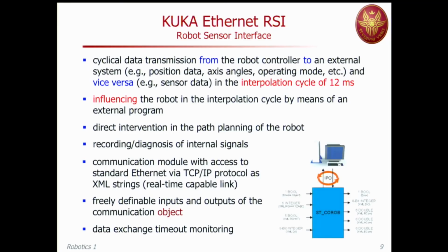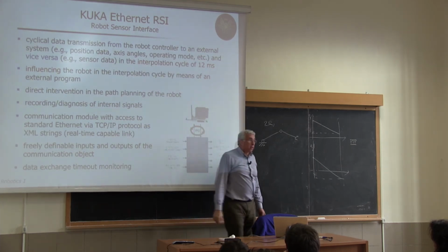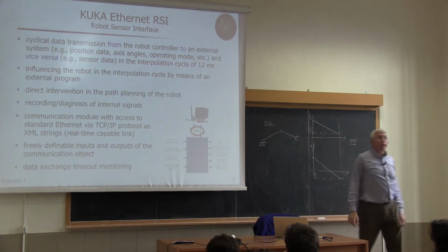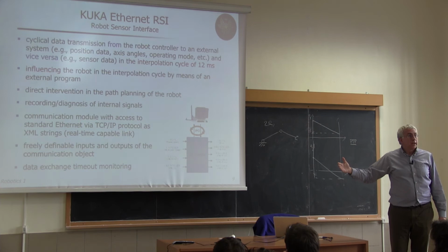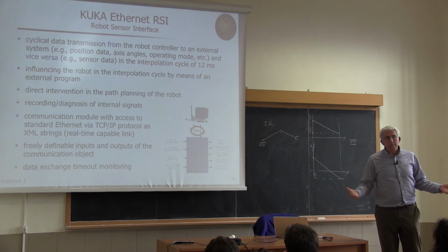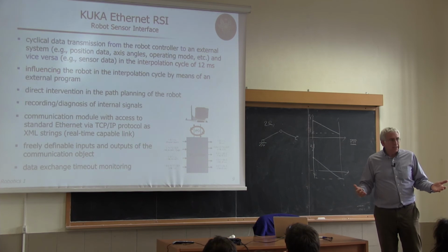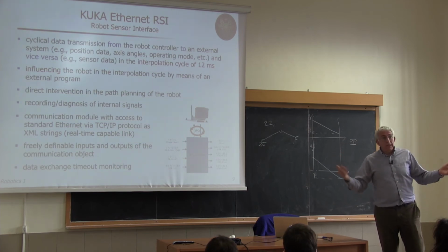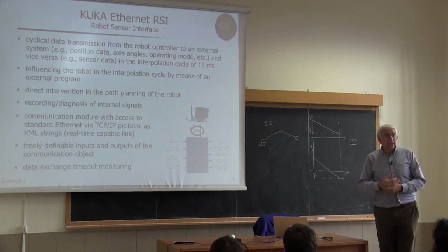And of course, there's a monitoring of timeout, because if you allow command data to enter from your own program or acquire sensor information from your external sensor, then you have to respect this limit of 12 milliseconds. If you take longer than that, some strange effect may happen, because the KUKA controller may read whatever is on that port at that instant, which may be a signal without any significance, or it may be stuck waiting forever for a signal that is not coming.